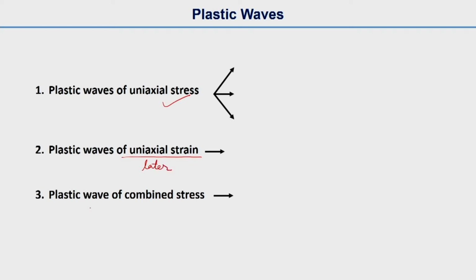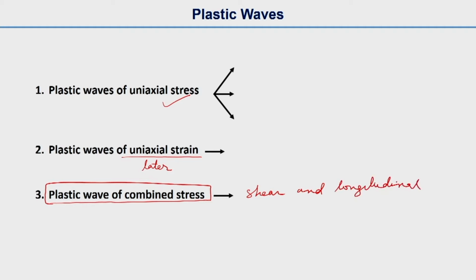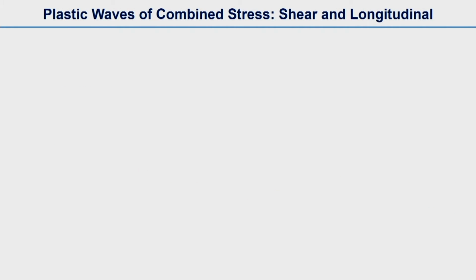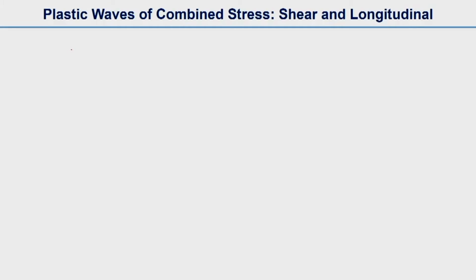And today we will discuss the plastic wave of combined stress, that is both shear and longitudinal plastic waves. So plastic shear wave, like the elastic shear wave, involves the particle displacement in a direction perpendicular to the direction of propagation of the wave.